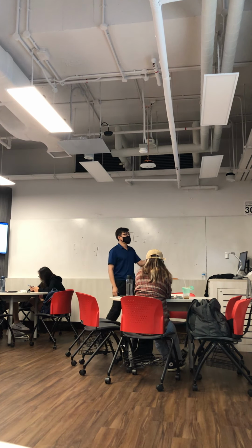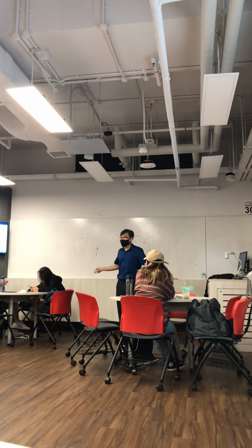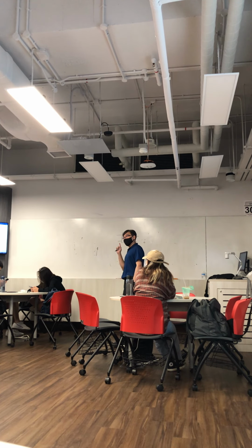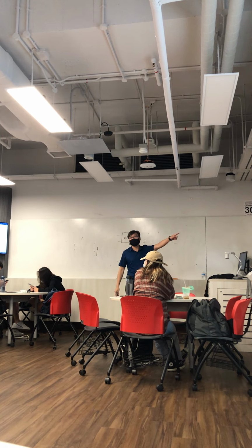Okay, so you can make an impulse there, and then apply it as the input to this system. You measure the result. It can be a time varying thing. Although you apply one impulse, based on the system you can have quite a complicated response. So that is called the impulse response, and I call it h(t), for whatever linear system there.